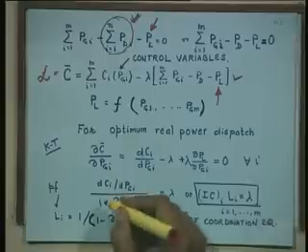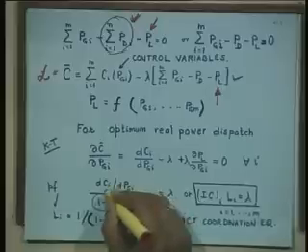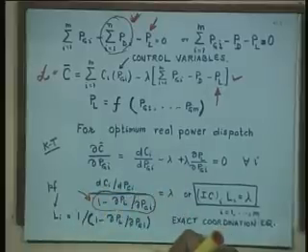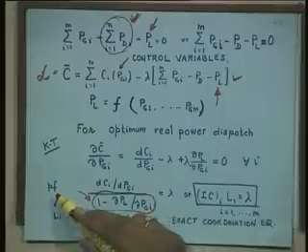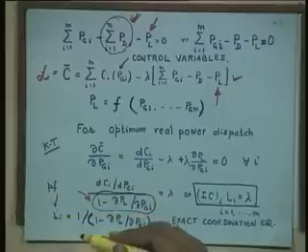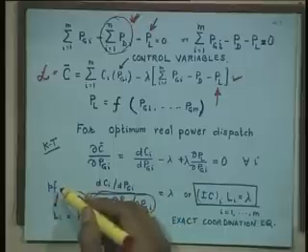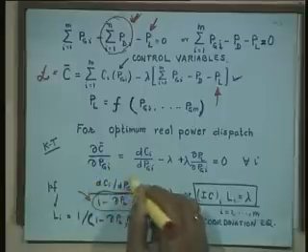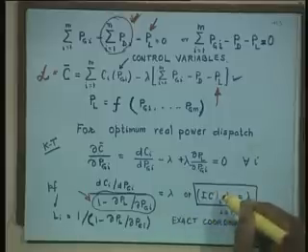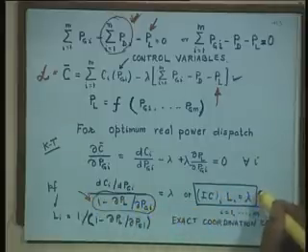All of you are intelligent, that is my assumption, and I am sure my assumption is not wrong. This is the only term which was not there earlier on. This thing was there earlier, so this is a new term, and this 1 upon this is called Li, the penalty factor, PF, not power factor, penalty factor. I can briefly write the numerator as IC, incremental cost of i, into Li. Li is a penalty factor, it should be equal to lambda.